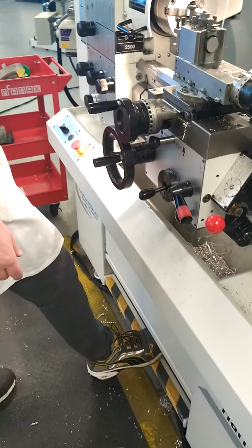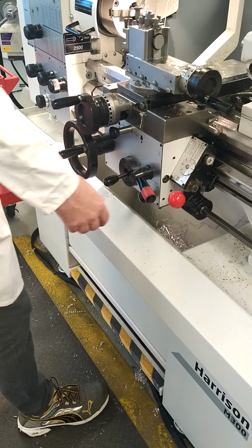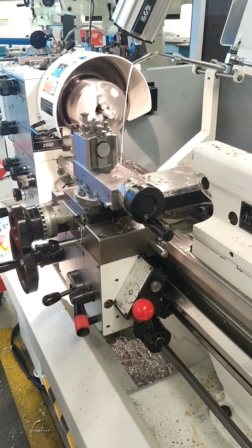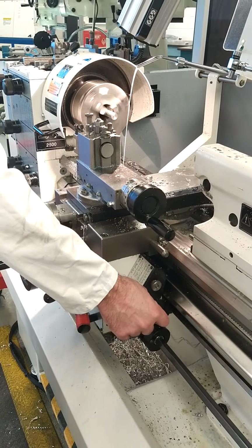There's an emergency stop brake underneath, but generally you're never going to let the machine come to a stop on its own. If you move out and up, that's going into reverse. 90% of the time you're always machining down, with the lever out and down, the work turned onto the tool and we're cutting. So now let's look at the next stage. We'll be installing a cutting tool.